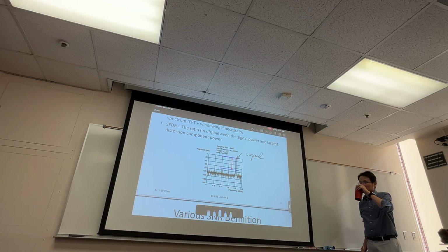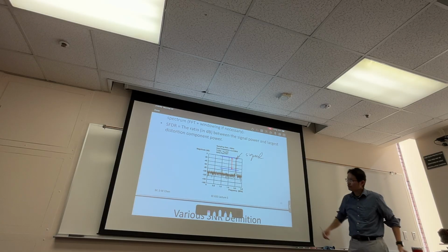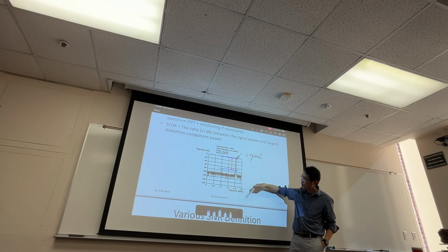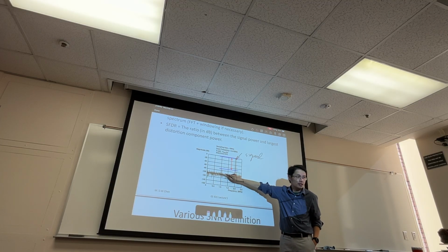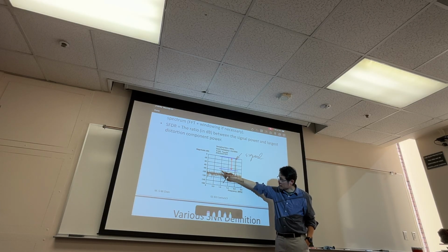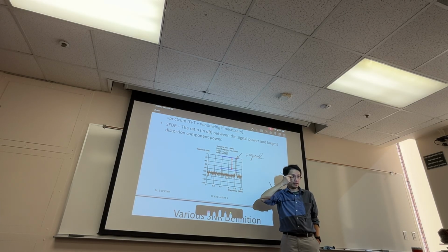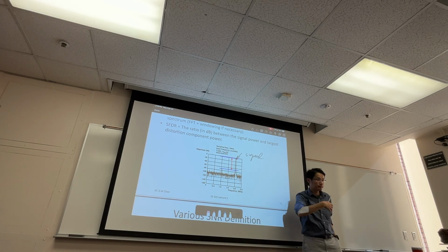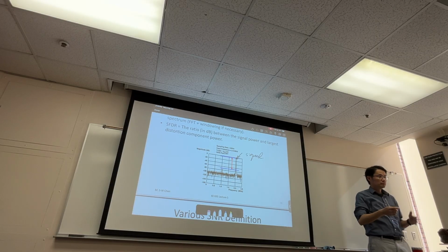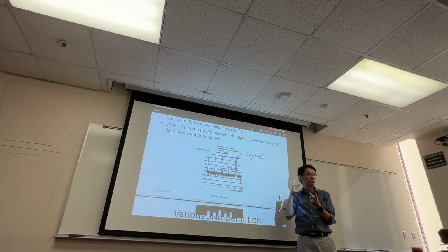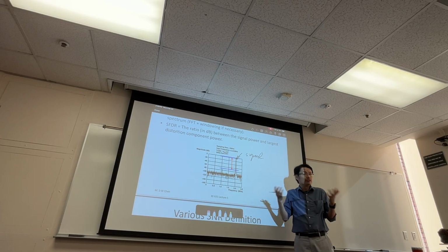So let's go back to this. How do I compute the SNR? First of all, you sum up the signal power right here, right? Next, you sum up all this noise, but you don't include this because this is coming from the distortion. But you sum all the rest of the noise, and that's your SNR. Now that noise includes quantization noise power and also all the circuit noise. So it's everything, right?